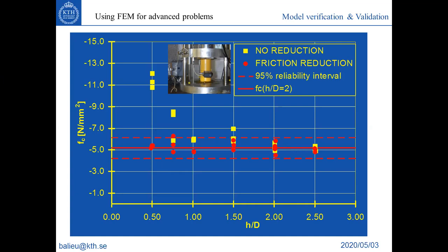This is not correct, because you are performing a simulation. Let's say this is an asphalt concrete specimen. You characterize this peak stress, and afterwards you want to model an entire pavement. It's not a cylinder anymore. There is no such geometry ratio. So you cannot use this one or this one. You have to use an intrinsic material parameter.